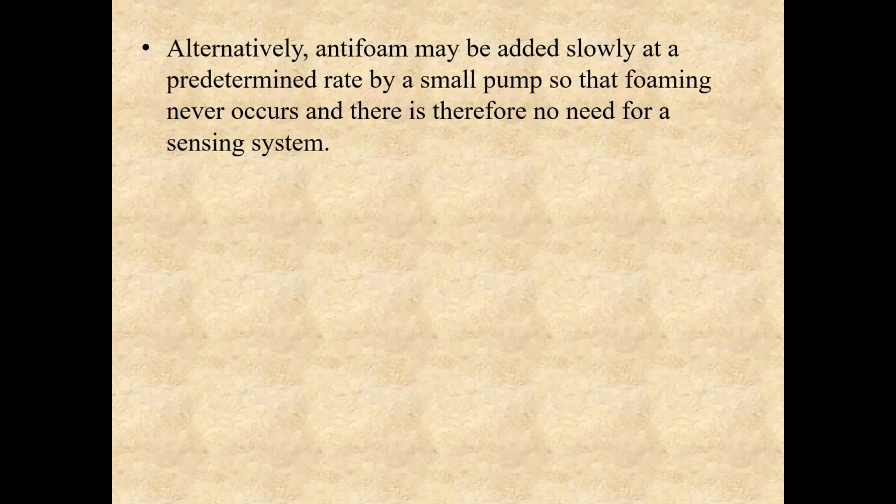But you would say there's an advantage to adding an antifoam into the fermenter, because otherwise foaming may lead to loss of fermentation. Yes, but the antifoams have their own disadvantages. Unfortunately, the concentrations of many antifoams that they use in industries reduce the oxygen transfer rate by as much as 50%. Therefore, antifoam addition should be kept to an absolute minimum. That's why many may not go for this system.